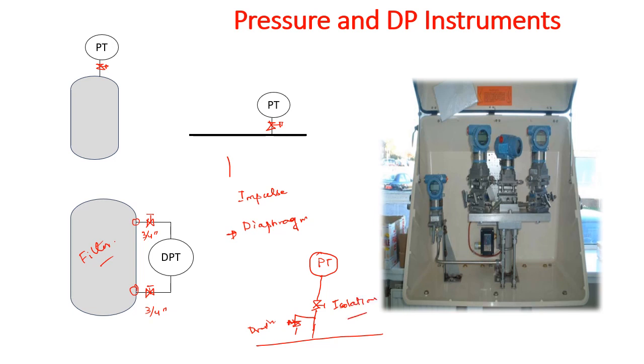Okay, so another thing is PG, pressure gauge. Pressure gauge is like this one, and it can be shown as a PG, or in some places you will see that it is shown as PI also, like pressure indicator. So it is shown like this. Now in some cases from the same tapping, both PT and PG are shown. So how that looks like, see,